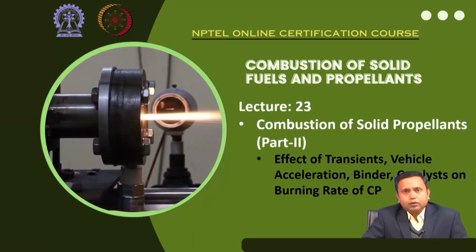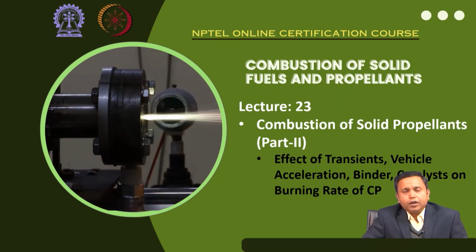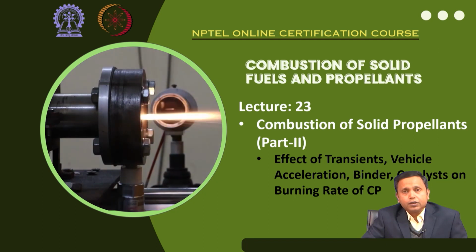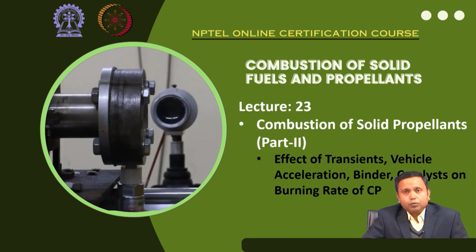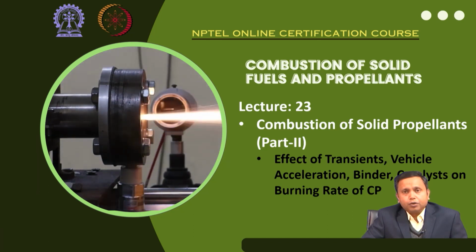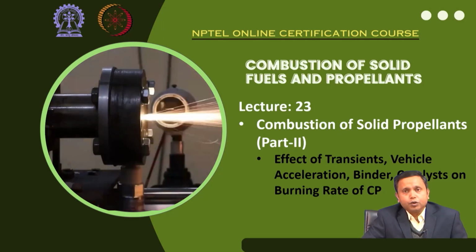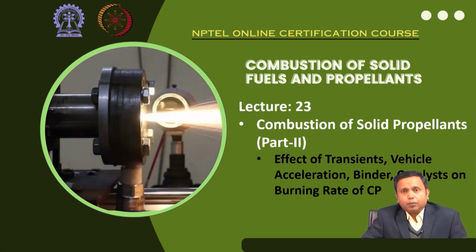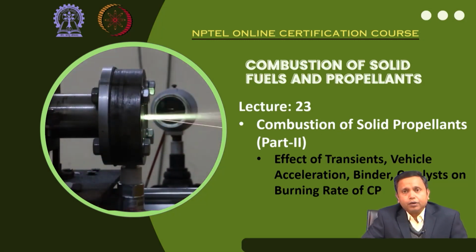Hello everyone. So, we were discussing the various effects on the burn rate of composite propellant. We have already discussed the effect of pressure and the effect of ammonium perchlorate particle size on the burn rate of composite propellant. We also talked about the effect of the initial temperature of the propellant, because the propellant gets heated by receiving heat from the flame.